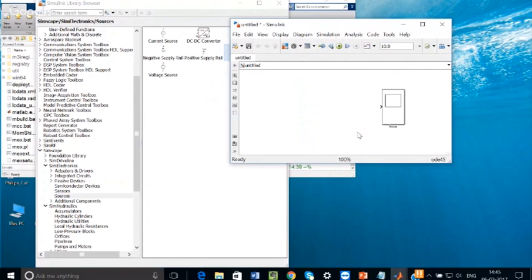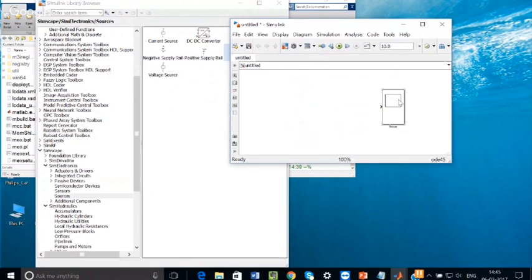In older versions, wind power modules like DFIG and all those things are present. But now, if you see the latest version, there's a common solar module available that is in the demos. They have not put it here, but if you take the solar module from the demo and put it here, you can go and change all the characteristics, the open circuit voltage, the short circuit current, and everything can be changed. That is in the 2016 version, it is already available. Okay, so these are the things.